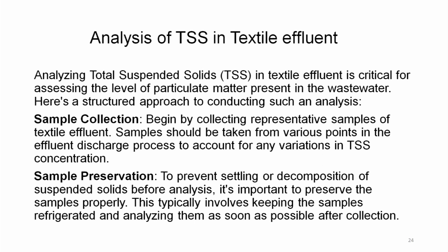Sample preservation: to prevent settling or decomposition of suspended solids before analysis, it is important to preserve the sample properly. This typically involves keeping the samples refrigerated and analyzing them as soon as possible after collection. So, ideally they should be analyzed immediately, but if it is not possible, they should be kept under refrigeration.